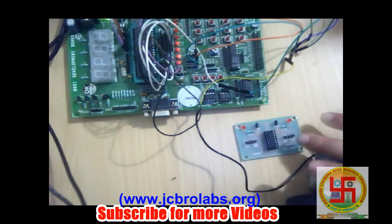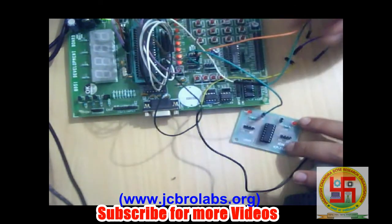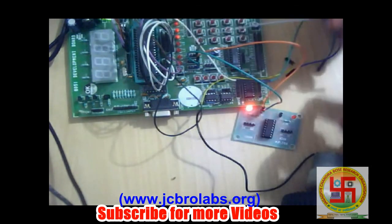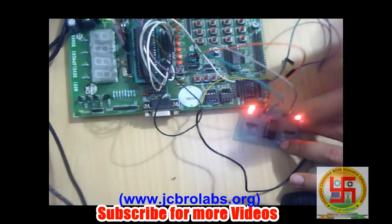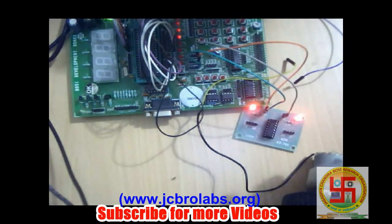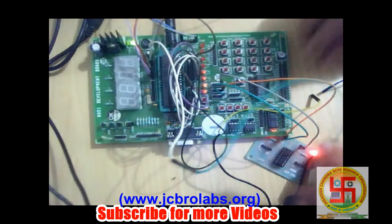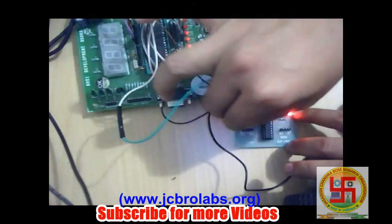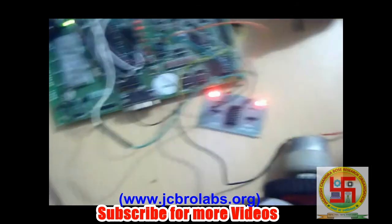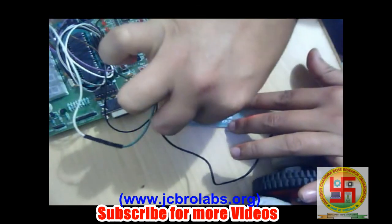First let's connect the power supply. This is +5 and this is ground, and this is +12. Now this particular pin is P1.1 of the microcontroller. It is coming from here, P1.1, and we will connect this particular wire to D0 of this PCB. And this is the P1.0 wire, which we will connect to the second pin.